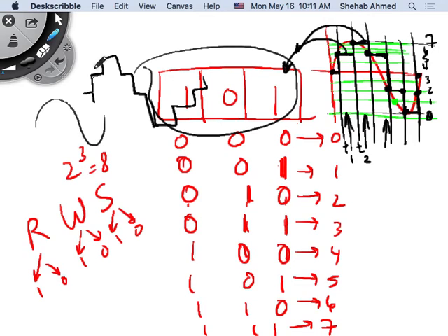So that's why you want clock speeds that are super high, and you want a number of bits that is very large, because you want your information not to be lost. You want to be able to look at the screen, because again, your screen output is analog. At the end of the day, this transducer, this screen that you're looking at, is analog. This is the interface between you and the computer. You're seeing this analog signal. It's not the digital signal that's happening, right? So you want to see a nice signal. You want to hear nice audio, right? So this is going to depend on the sampling frequency and the number of bits of the computer system.